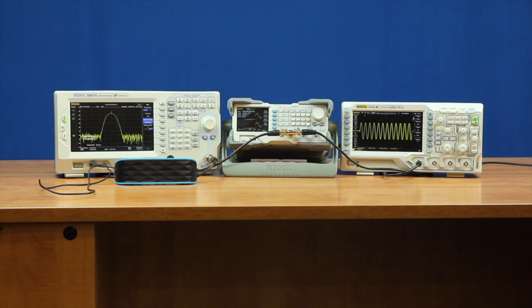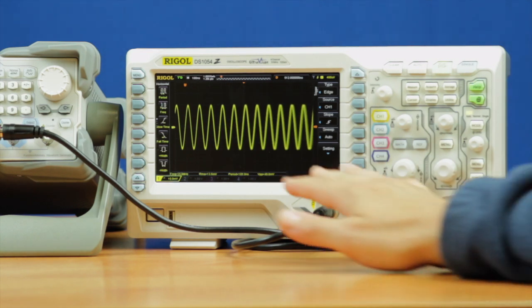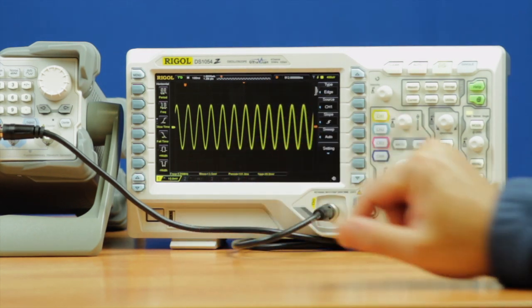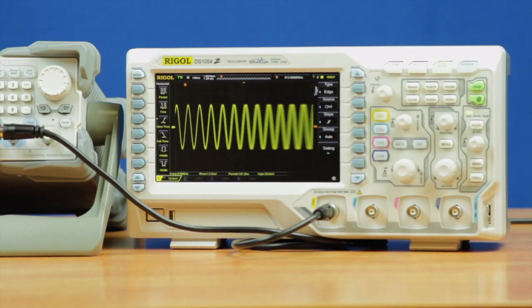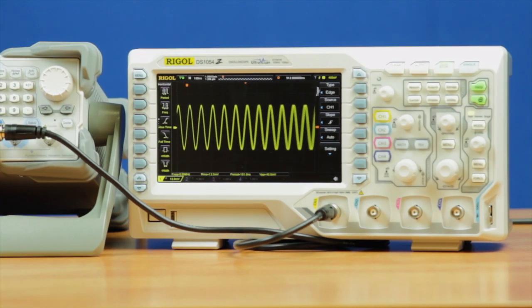So now I've changed the setups to load the FM external setup files. Now we're loading the same audio, externally modulated, this time as frequency. On the scope, I've moved the trigger over to the left side so we can see how the frequency changes over time. You can see the modulations as you get about 5 or 10 cycles, but again, the spectrum analyzer can pick those up more clearly.